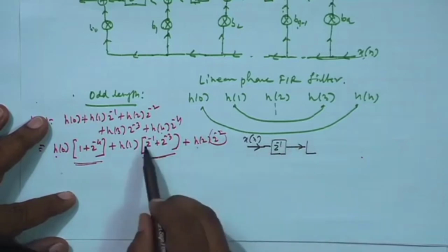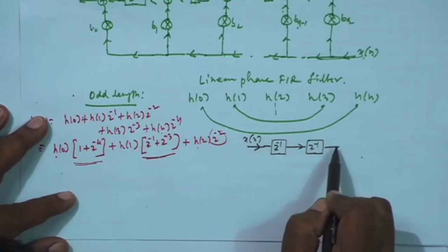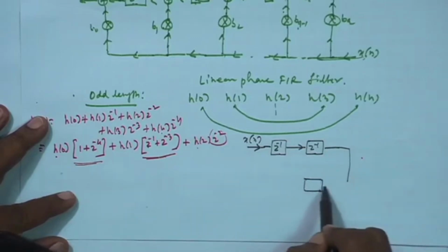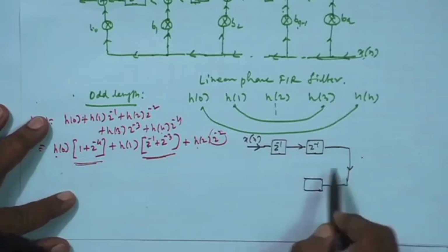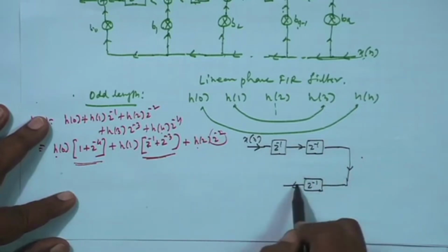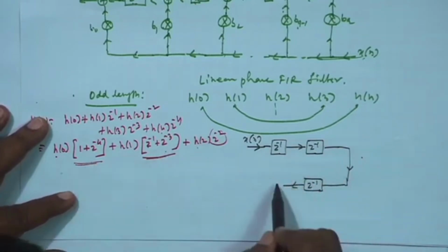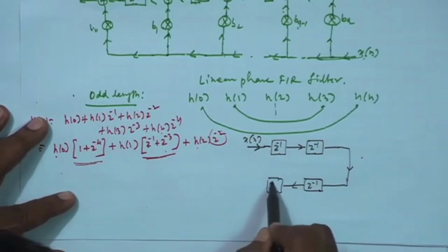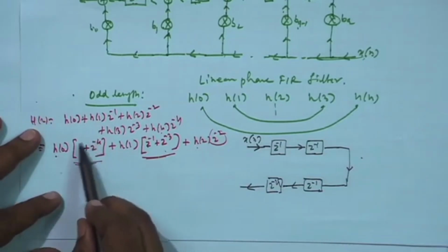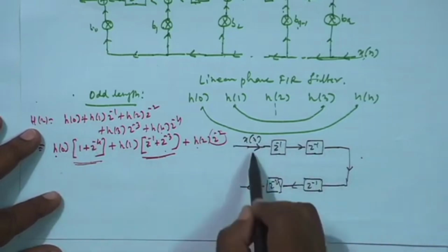So, this is Z inverse coming, Z inverse 2 coming, put another Z inverse. So, Z inverse 3 coming for this, and there I need another delay Z inverse 4. Now, X(z) into 1 plus Z inverse 4. So, X(z) and Z inverse 4 times X(z).